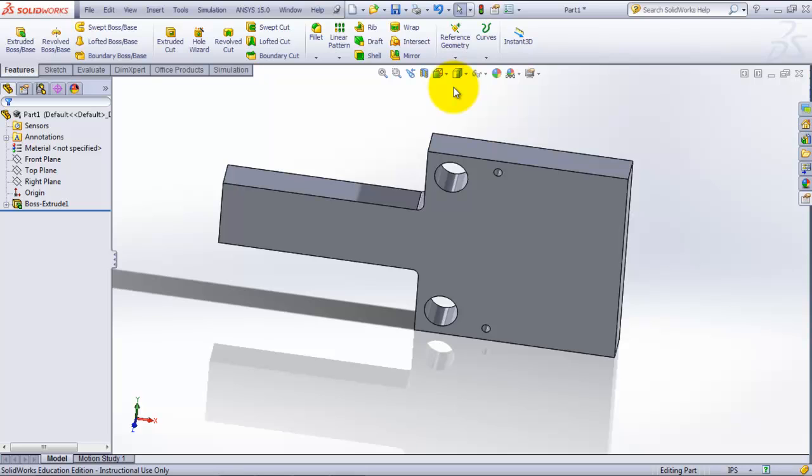So if we want to take this into ANSYS, actually anything we want to do to get this over to ANSYS, we need to save it first. So you can run into issues and it just won't show up and stuff like that. It may or may not give you errors to help lead you in that direction. Easiest thing to do is just save this.